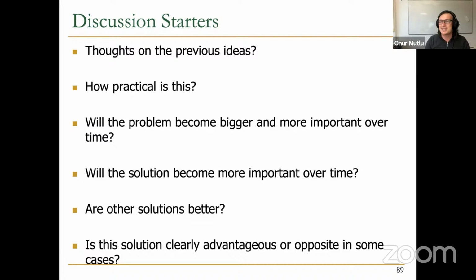In the general purpose case, yes, the operating system needs to be aware. But I would argue that there are a lot of good reasons for the operating system to be aware of banks, for example, and subarrays going into the future, so that you can optimize. Since memory is a big bottleneck, I think it makes sense to make operating systems and potentially applications also be aware of the topology of DRAM, so that you can schedule applications better. You can map the data better to different subarrays, different banks, such that applications do not interfere with each other, for example. We may cover memory channel partitioning later on.